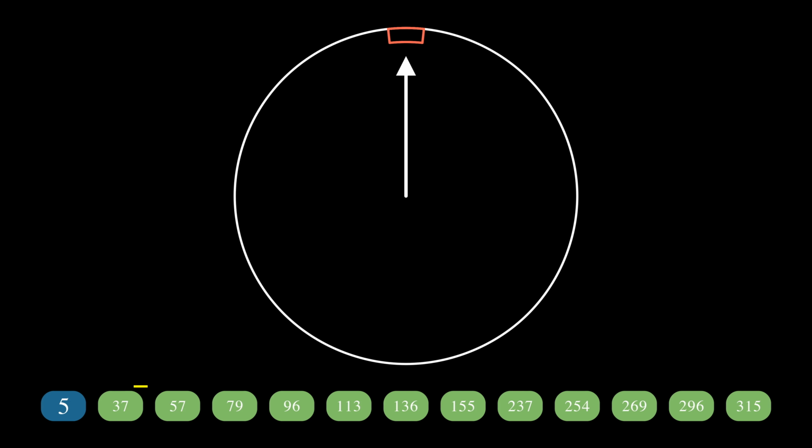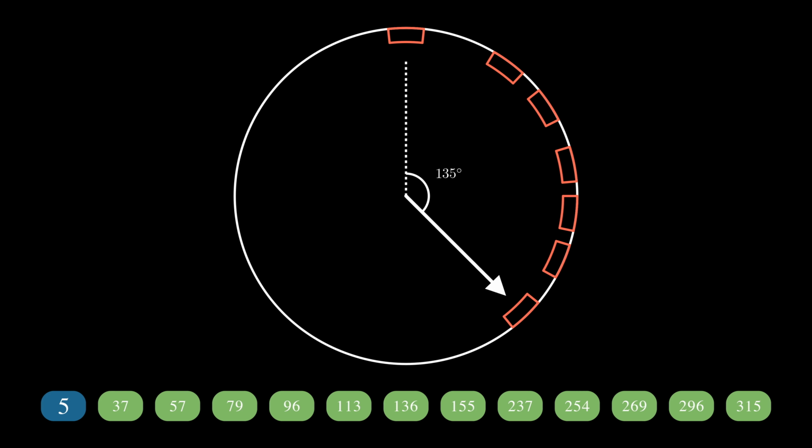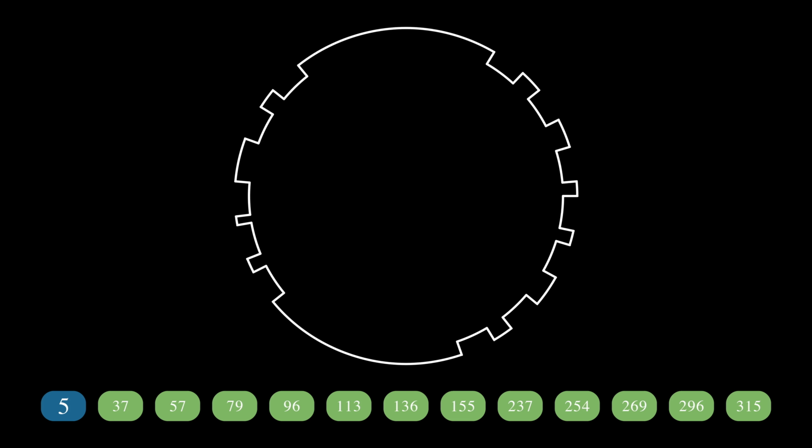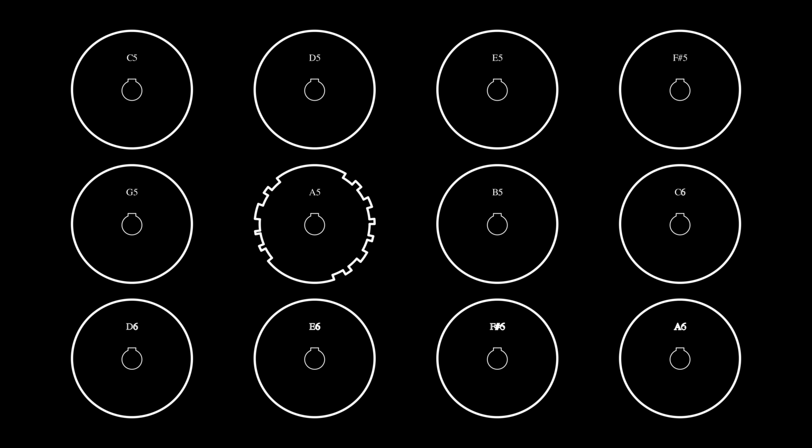The script looks at all of the angle values in that row and passes them into a circular pattern that creates an instance of that solid body at every angle. The initial reference cutout is deleted, and all of the other bodies are Boolean subtracted out of the main cylinder to create the cam's shape. The custom feature then sketches and extrudes a bore and key slot based on our specs, and writes the note number based on the index of that cam in the CSV file. As it iterates through the rest of the rows, it repeats the process and creates a unique cam for each one.